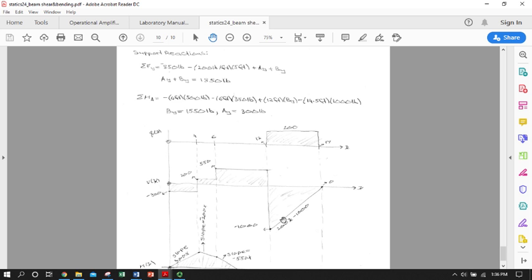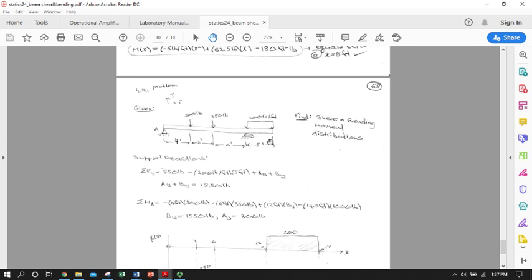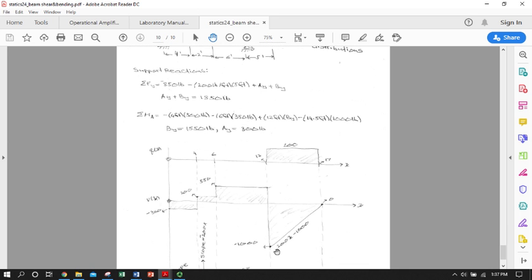So the slope of this line equation is the same as the level of the distributed load here. So this will be 200x, and then we'll figure out our B based on what it would have to be to start at negative 100 and end up at V equals 0 at x equals 4, 6, 12, 17. Or we could just define it by itself on this interval as 200x minus 1,000.